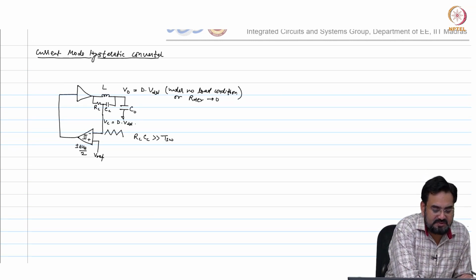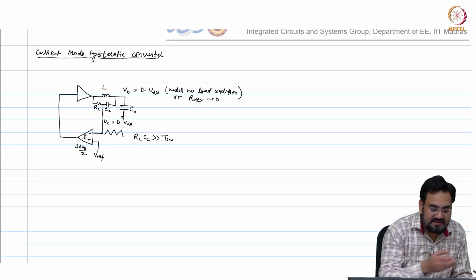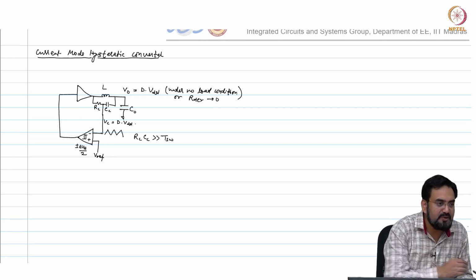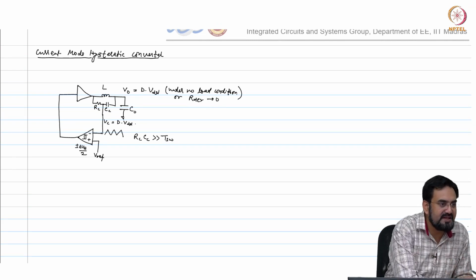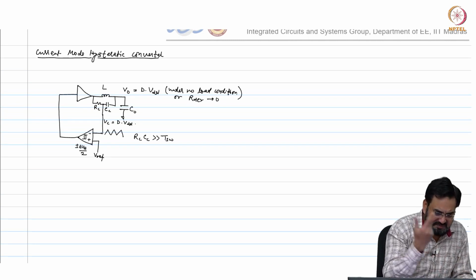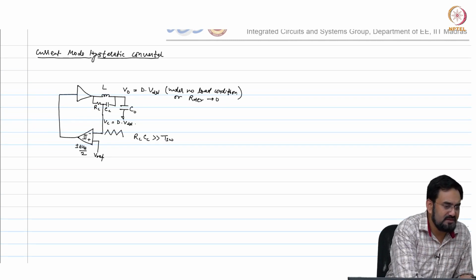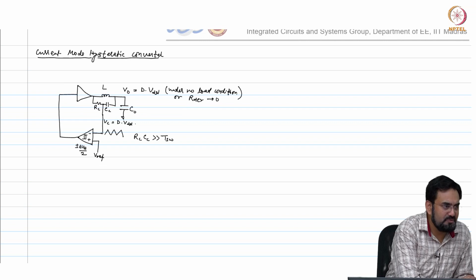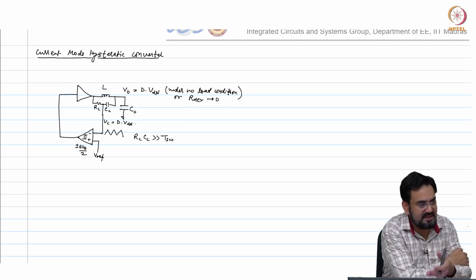What about the transient response? And the other good thing is that now you are not depending on the output ripple. The hysteretic window we were keeping was based on the output ripple required. Now, I can keep this 50 millivolt or 100 millivolt, and it will not affect your output ripple, correct. Output ripple will always depend on the switching frequency and this LC filter.